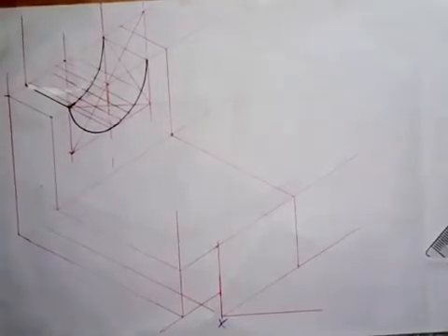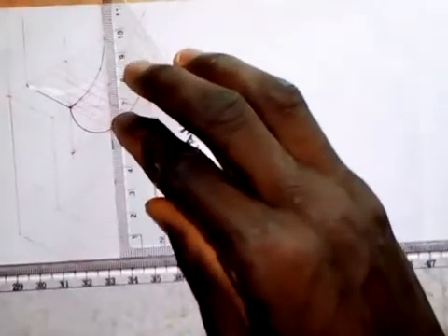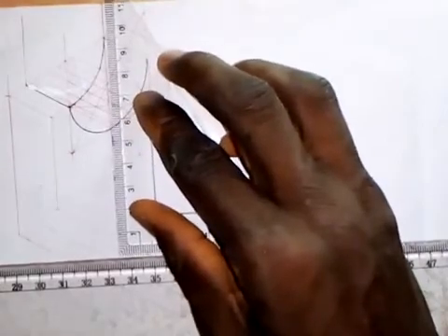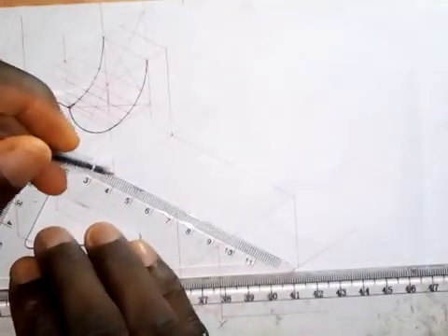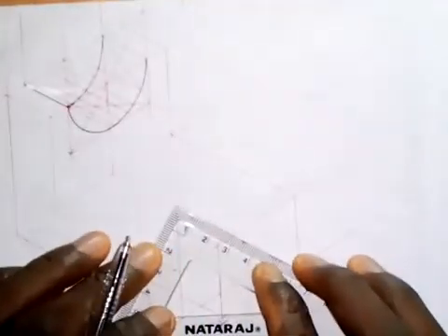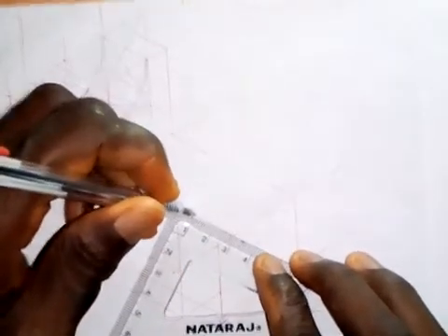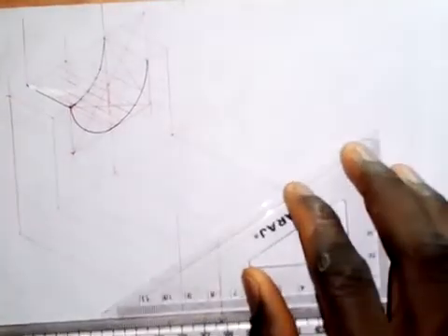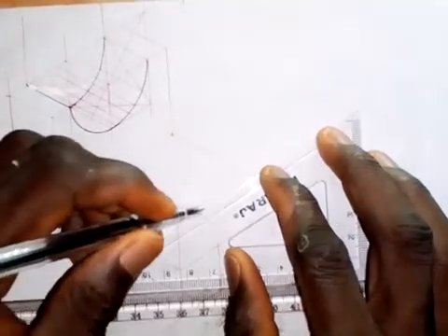So the next thing I'm going to add here is the web. So the web, as we have in the diagram, is in the middle here. It's in the center of the object. So I also need to transfer it to this side. The web ends at a distance of 20 millimeters from this end. So you take a measurement of 20 millimeters from here, and just draw a line, like this.